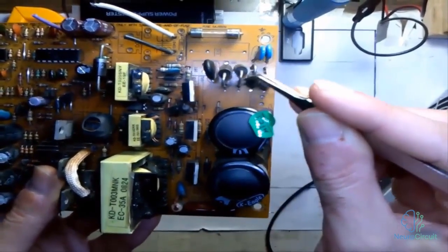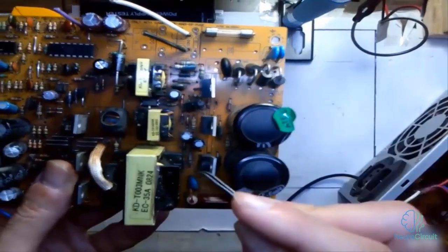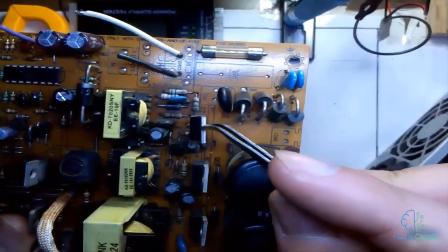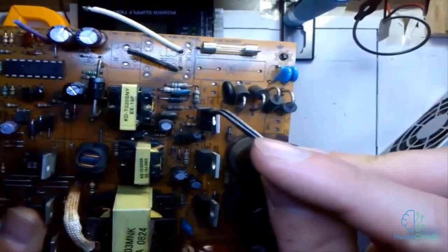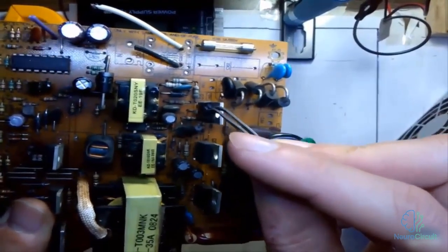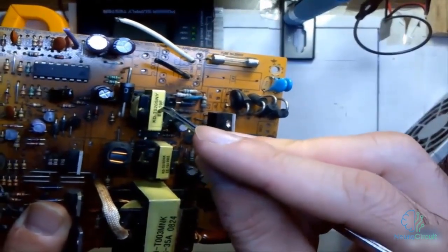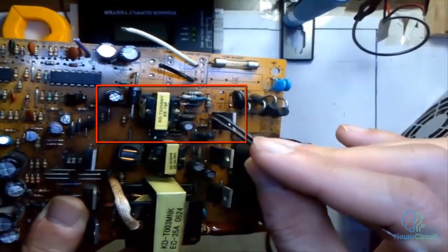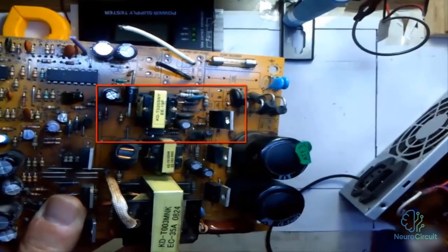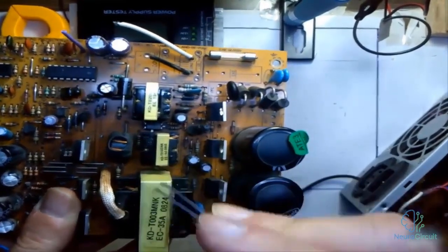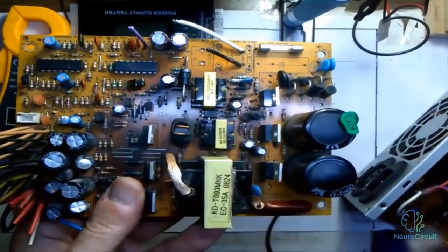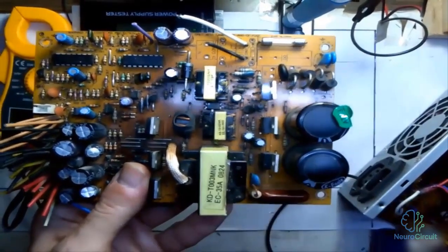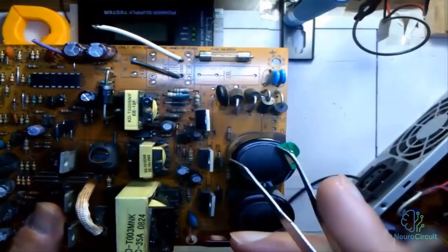In these power supplies, there are also diodes and transistors located here, especially the two transistors you see here, because the primary transistor you see here is the transistor related to the standby circuit. This transistor is a FET type, and this transistor you see here is related to the standby circuit, and overall this section is the standby circuit of this power supply. The next transistors are related to the output voltages, which generate the required voltages here and perform voltage reduction. In fact, the transformers here are step-down types, so up to this point you've learned that.